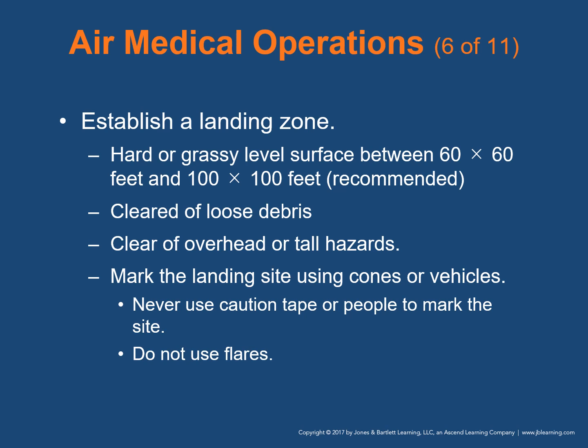Establishing the landing zone is the responsibility of the EMS crew, so an appropriate site for a landing zone should be a hard or grassy level surface, 100 by 100 feet, which is recommended, but no less than 60 by 60 feet. It requires a minimum of that for rotor clearance. Also, because of rotor disturbance and turbulence, the area must be cleared of loose debris such as branches, trash bins, flares, accident tapes, medical equipment, and supplies. And it should be clear of overhead or tall hazards such as antennas, trees, telephone poles, etc.